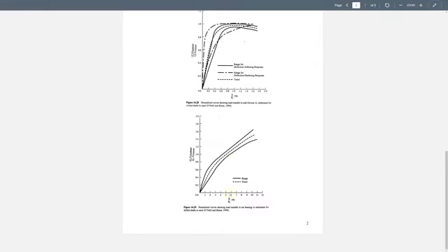You realize the sand curve versus the clay curve can have a significant difference. Those dictate the shape of the curve, and you need to find your own Q max and F max to apply to that. The x-axis is the settlement normalized by the diameter. The B sub B right there is the diameter of your piles.